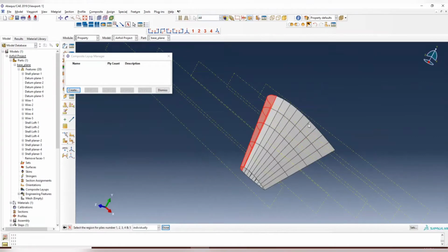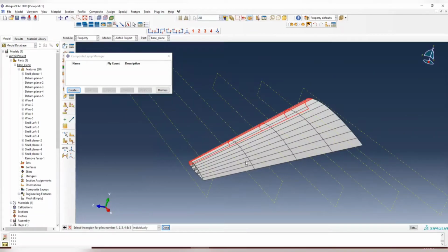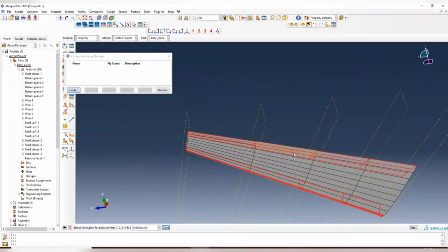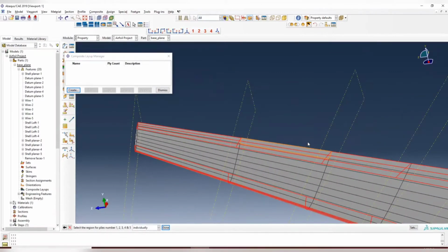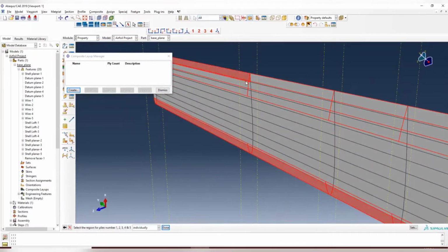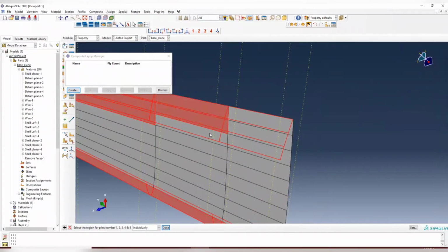These 4 should be the airflow ridge. And then we select everything after 0.7. So 3 of them, because each interval is 0.1 of that. Hold shift to select all of that. And if your geometry has some problem, you can hold control. For example, you select the wrong one, you can hold control and deselect that. That's a little bit hard to select, but should be this. And click done.